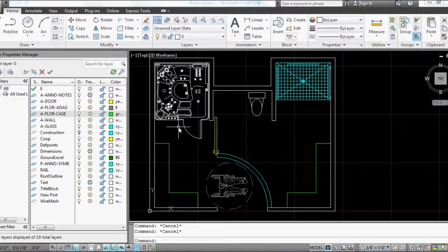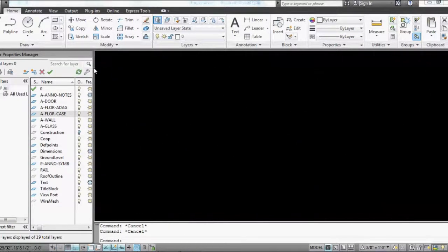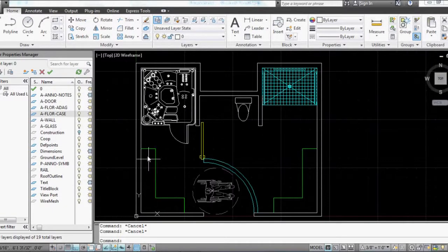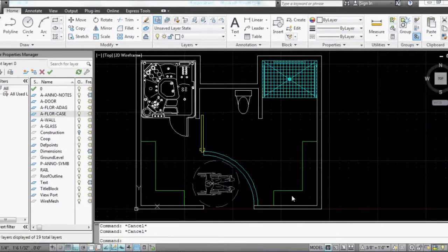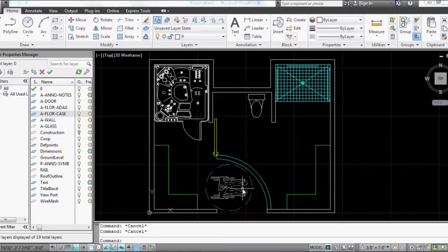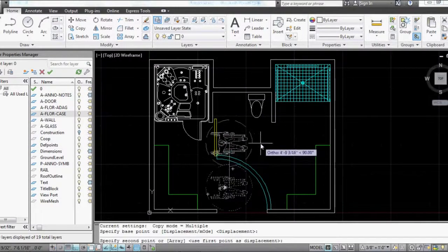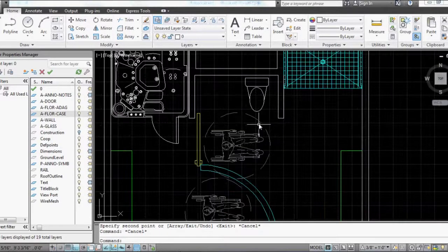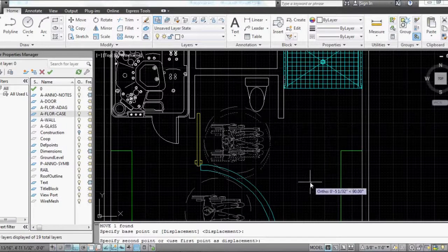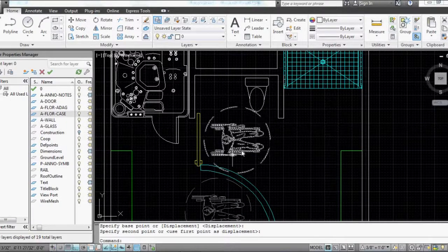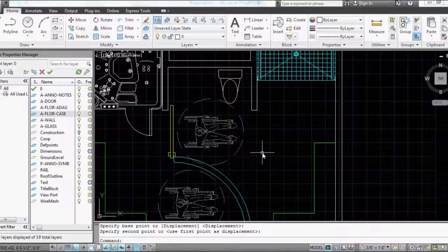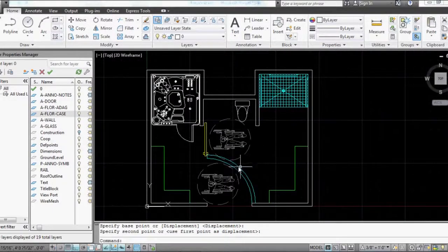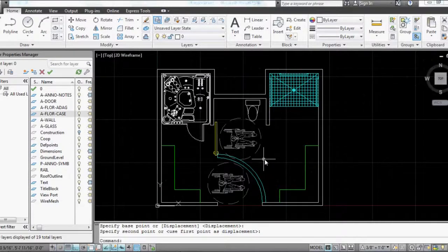You have to start rough, so we eyeballed a few things like these dimensions, but overall we're just starting to get things into the computer, into a scale, and making sure that things don't conflict. We want to make sure that this wheelchair radius doesn't present problems, and you can kind of see that in this restroom area, in the WC area, that might become a problem, right? He doesn't have the necessary room to turn around clearly, so we might have to redesign this wall a bit. But this is how you can see we build up our drawing from just an outline and begin to work out details like that.